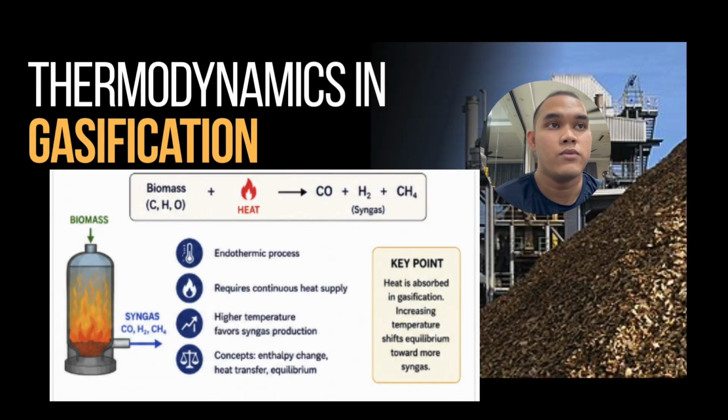Gasification is strongly influenced by thermodynamics because it is an endothermic process. The overall reaction can be represented as biomass plus heat plus limited oxygen produces syngas consisting mainly of carbon monoxide and hydrogen, together with smaller amounts of carbon dioxide and methane. Because it is endothermic, heat must be supplied continuously for gasification to occur. When temperature increases, equilibrium shifts and promotes greater syngas production. Important thermodynamic concepts include enthalpy change, heat transfer, and chemical equilibrium. By controlling temperature properly, syngas production can be maximized and process performance can be improved.